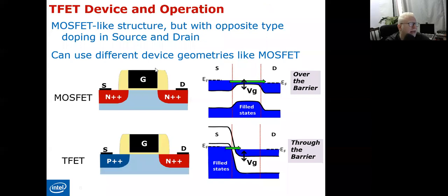So if you examine now the junction you are examining here, let's mark out the line. So this will be your junction. It's a PIN junction. P is the source, I is the substrate, the intrinsic substrate, and N is the drain. So now we turn the junction from being an NPN junction to be a PIN junction. But the question is, what is the benefit from having such an energy band diagram?